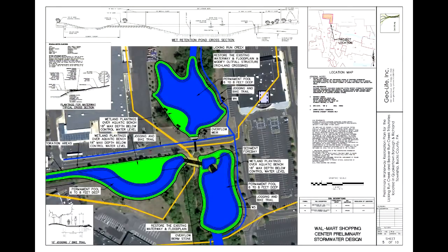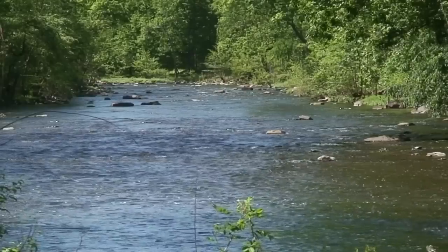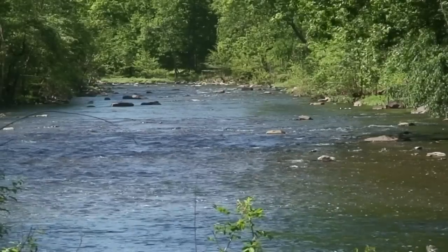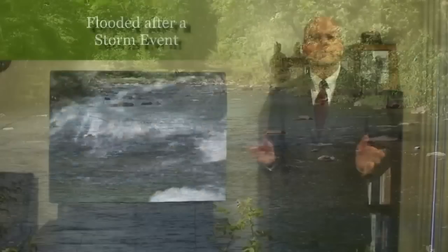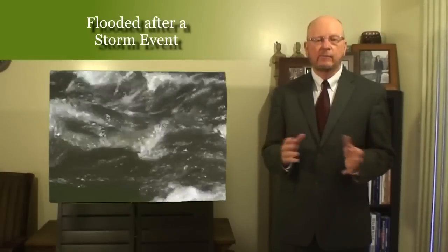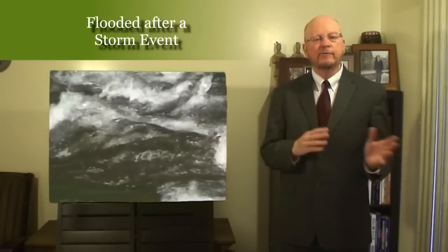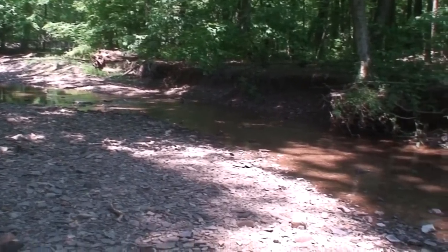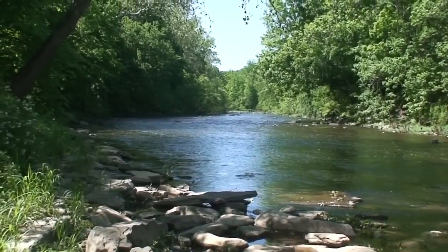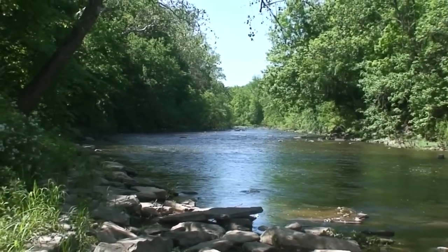The proposed waterway improvements will provide storage areas with natural vegetation to slow down and extend the stream base flow over a much longer period of time. This will reduce the tendency for the Licking Run Creek to be flooded after a storm event and then be dry the following week.